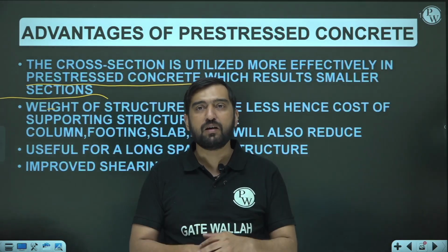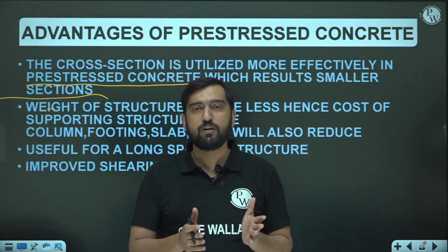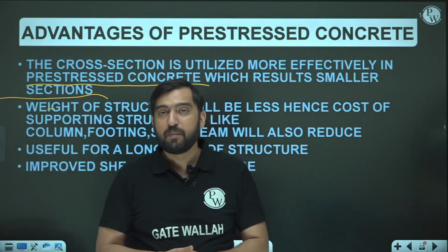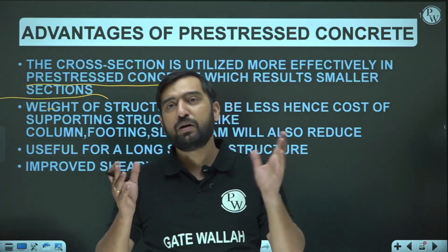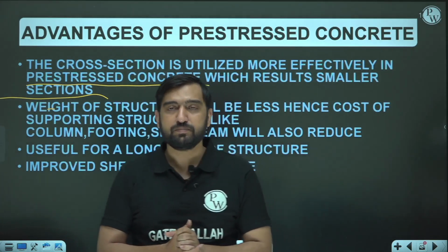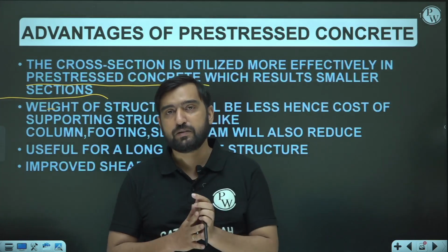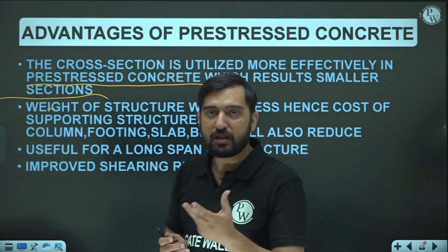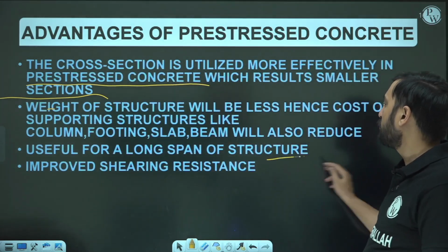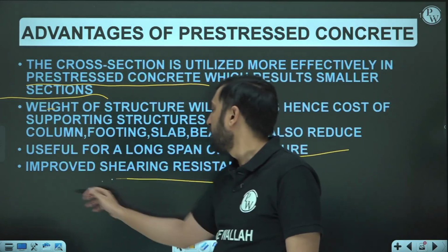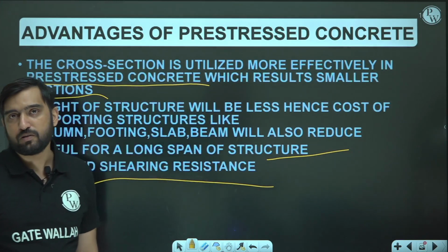Conventional RCC structures can be done with the help of experienced laborers, but for pre-stressed concrete you need literally a diploma holder type of people who can conduct that work, or they need special training for that, because equipment and stressing are sensitive things. So it is also useful for a longer span of a structure, and yes, I explained already, it improves the shearing resistance of the structure.